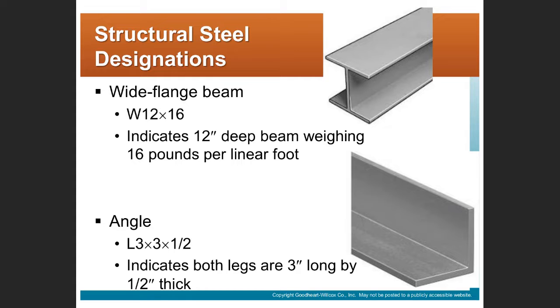Angle is also described. Here's an L 3 by 3 by ½ inch, right? 3-inch long legs that are ½ inch thick.